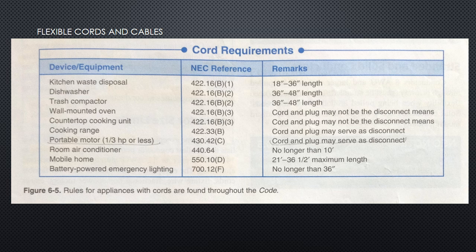400.5(A)(1). When using these tables, note that the equipment grounding conductor, neutral, and bonding conductors are not counted when determining ampacity ratings of cords. Cords and cables are permitted to be used as pendant wiring, fixture wiring, appliance connections, portable lamp or utility light connections, data processing equipment connections, elevator wiring and cabling, crane cabling, and hoist wiring.